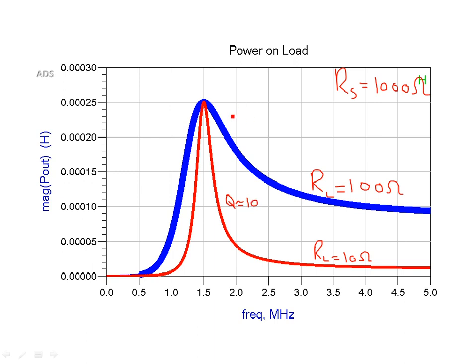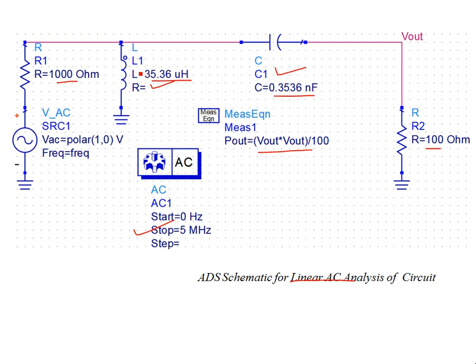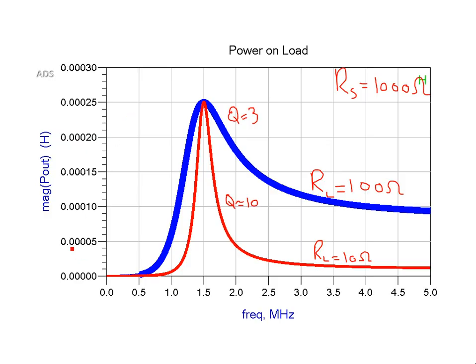or about 10. So the quality factor of the above curve has dropped to 3. So you see a very wide band match. And again, at DC, the behavior of the circuit is pretty much the same. At DC, the capacitor opens up, the inductor is short, so there is no power being transferred. And then at high frequency, there is a mismatch. So this is your mismatch region.